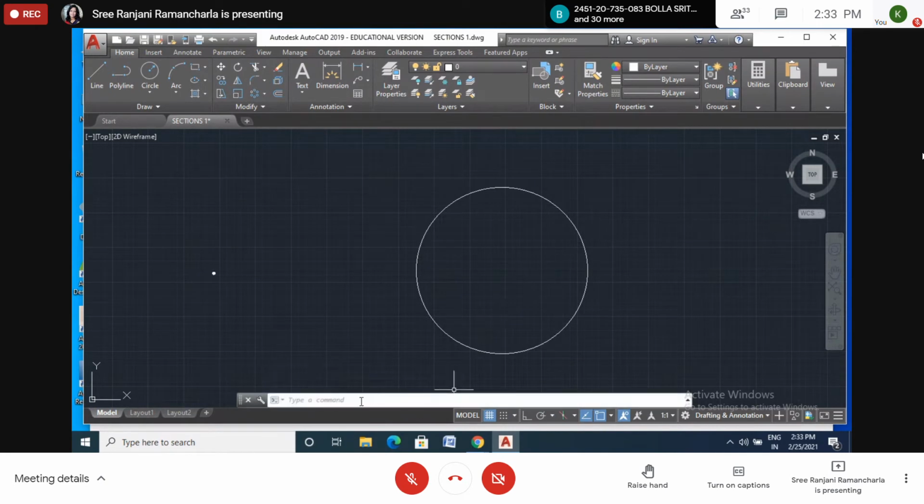You asked me to take a point? Divide the line. Okay. Divide the command, divide the line, divide the circle. Type div, enter. Select the object. Selected. Now enter the number of segments. So 12. Okay. Now these are all selected. There are 12 points, but the points are not seen. As we saw earlier, a point is like a dot, and that dot has coincided with this line. But how to know if the points are there or not? You choose any command here. Let me choose the line, then move over this circle.